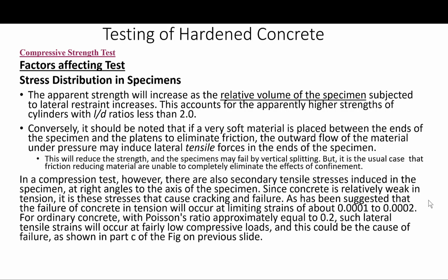We said the effect of that end restraint extends about square root of 3/2 of the diameter. So the longer the specimen is, the quicker the effect will die out, or be eliminated. In the case of the cube, it's not long enough for that effect to die out. So for a given specimen geometry, the higher confining stresses will also result in higher apparent strength.